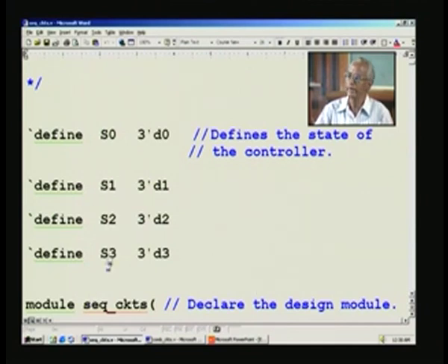while writing the code we can deal straight away with S0 and not the actual number. It is cumbersome to use a number at every point. So it is always easy to use a symbol like this, any meaningful name. That is why we can define using this directive, and this signifies this is 0. This is only for our readability. This decimal is what will ultimately reside in binary fashion, but while we deal with it, it is easier for us to resort to a decimal.